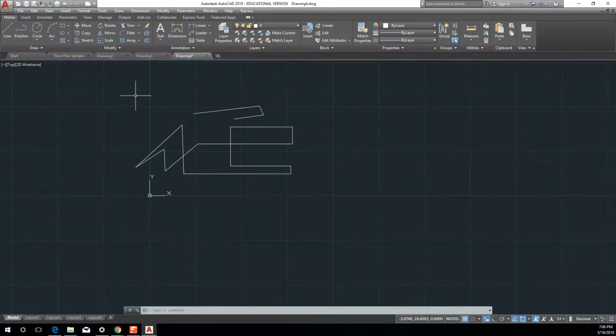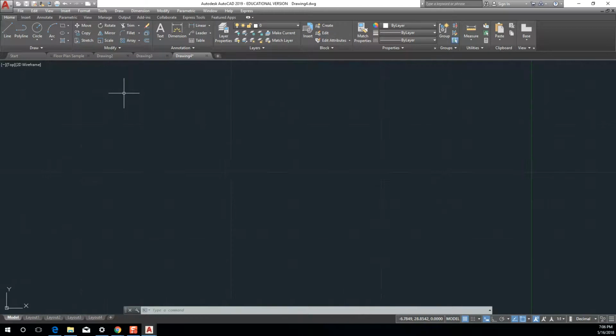Okay? If I get lost in AutoCAD, which sounds really silly, right? But it happens all the time, okay? I zoom in way too far and I pan about a little bit and I think, oh great, where am I? How am I going to zoom? Oh, nothing is working and I'm just lost and I can't find my drawings, right? I'm going to do what's called a zoom extents. A zoom extents will allow me to take my screen and zoom it out to the extent of every piece of drawn geometry on that screen so I can see everything, okay?